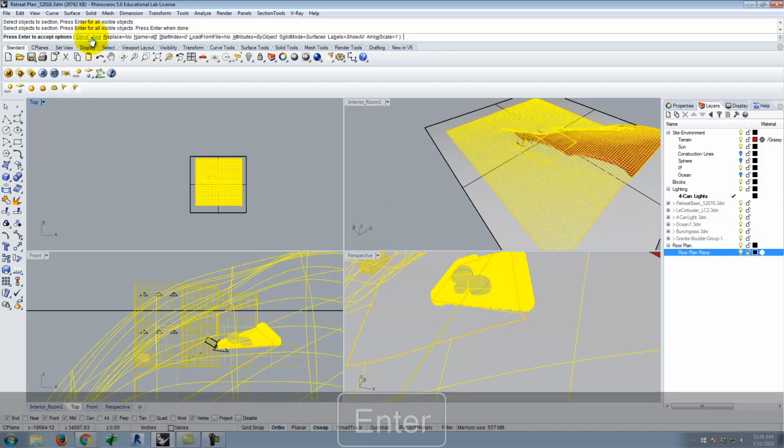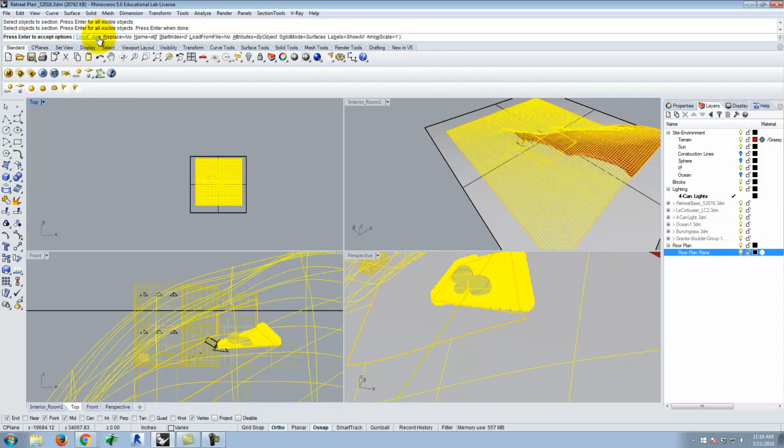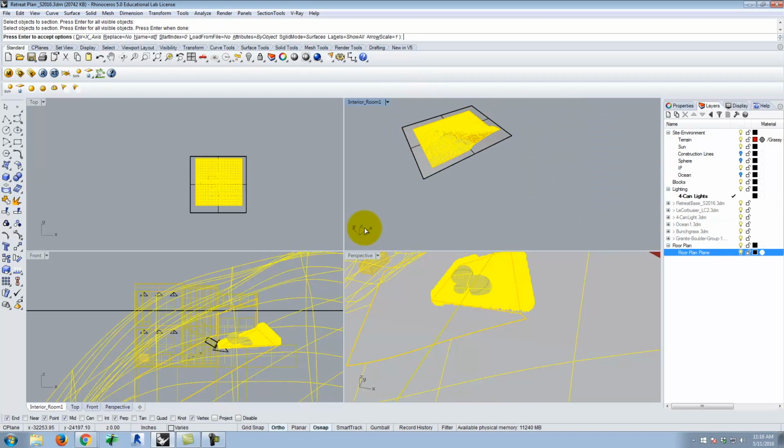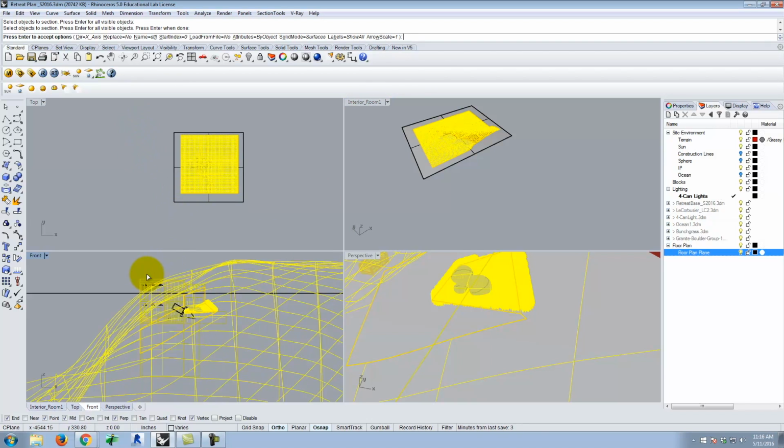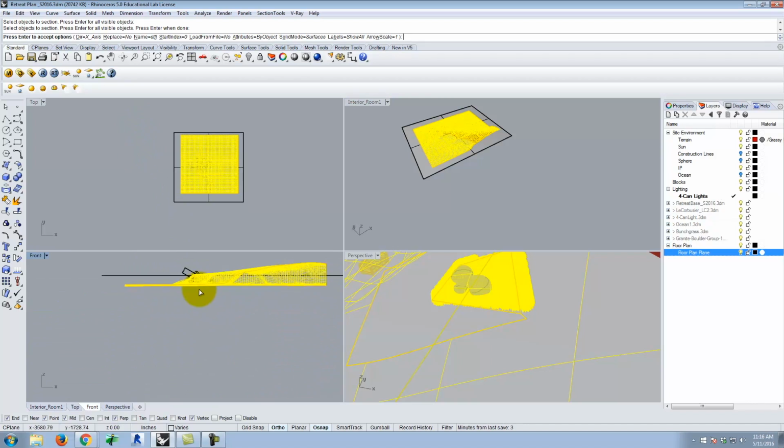And when I get to my x and my y axis, right, before we were working in the perspective view, so we were paying attention to, oh, it's going to be the x-axis, or it's going to be the y-axis, I'm going to pick an axis. In this case, I want it to be the x-axis, but I'm going to create the section in the front view. And so we can see here that it's the x-axis and the z-axis. So I'm going to work in the x-axis. That's good. We're going to make sure solid mode is set to surfaces. So I'll go ahead and hit enter.